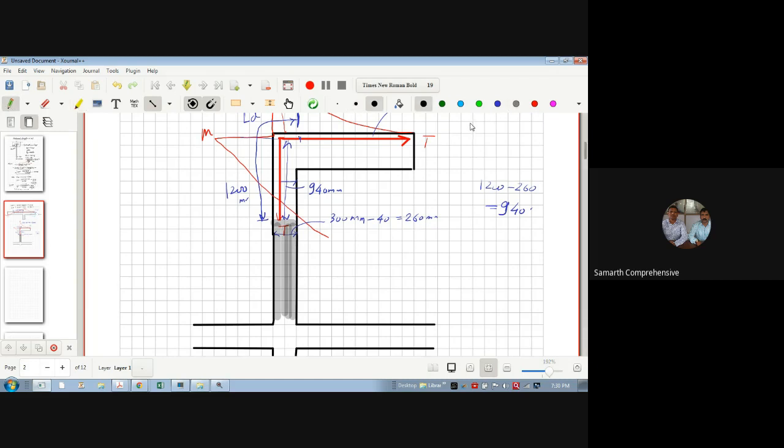All of you know construction. Generally we provide the bottom plate for the formwork or shuttering, we can say. Then I need to again create shuttering for the column here on both faces. Yes or no? And then I can cast this. But generally it creates problems on site. Partly casting the column and then the additional part, because there is a quality issue generally at this point. So at this point there may be quality issue.